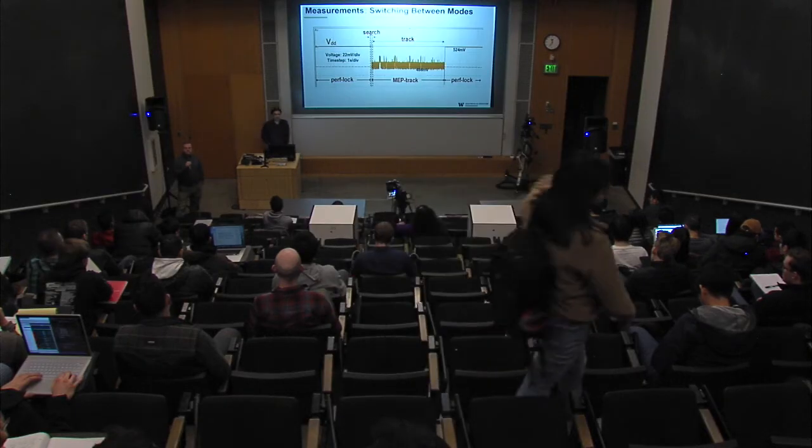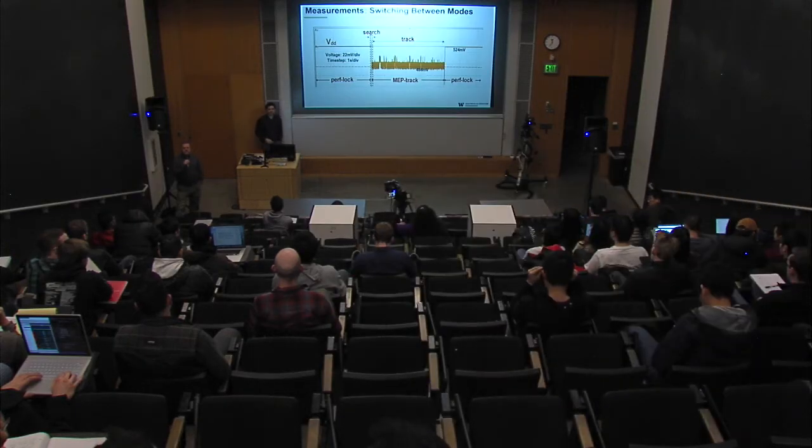So when you're actually trying different candidate voltages, that counts as noise. But the clock frequency of the system is adjusted in lockstep organically as you're dialing in voltage. So your voltage is your only independent variable, and your frequency becomes your dependent variable. It automatically adjusts so that you never fail timing. So yes, there is noise, but you can tolerate it because you don't lose function. More questions?